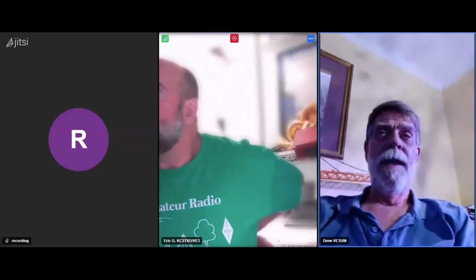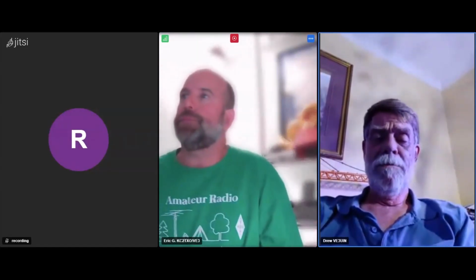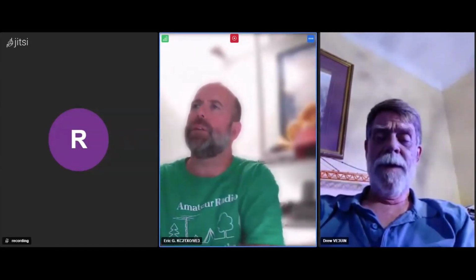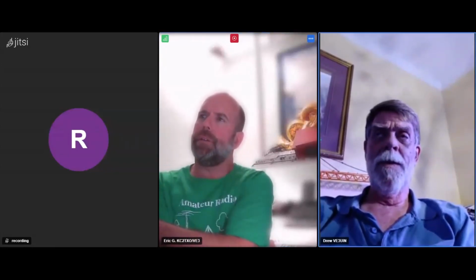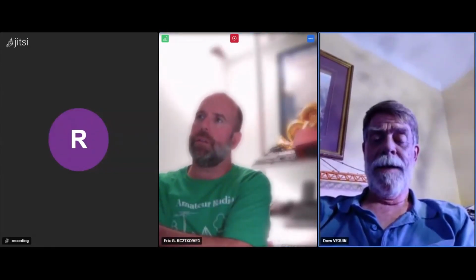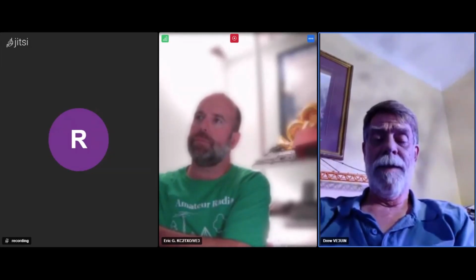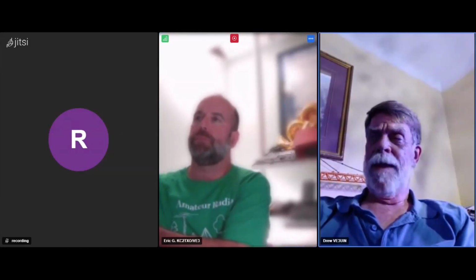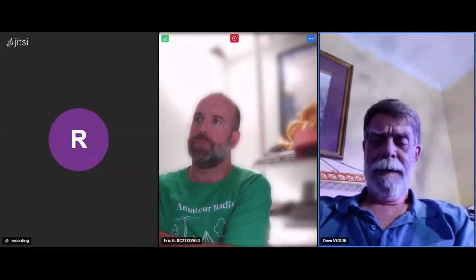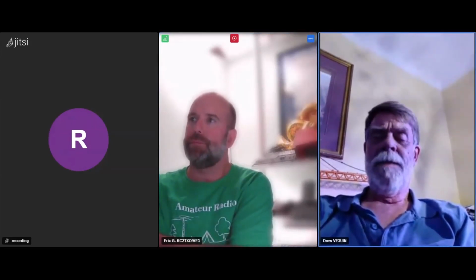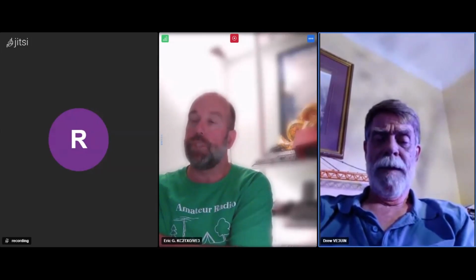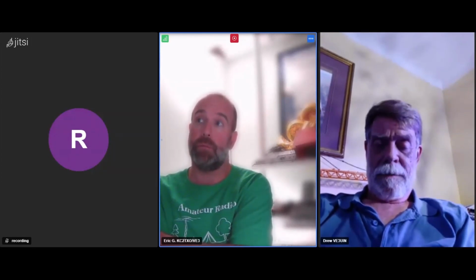Right. Which I have to watch because these little QRP rigs I have, if you put them into a mismatch, they blow up. They're really touchy that way. Everybody warns you, don't go over 2-to-1 or you're done. Several guys have reported the QCX is extremely sensitive. The one from Hans Summers, QRP Labs, I think. Yeah, apparently they're very touchy for SWR. So if you don't have a resonant antenna, you can do some serious damage to the radio itself.